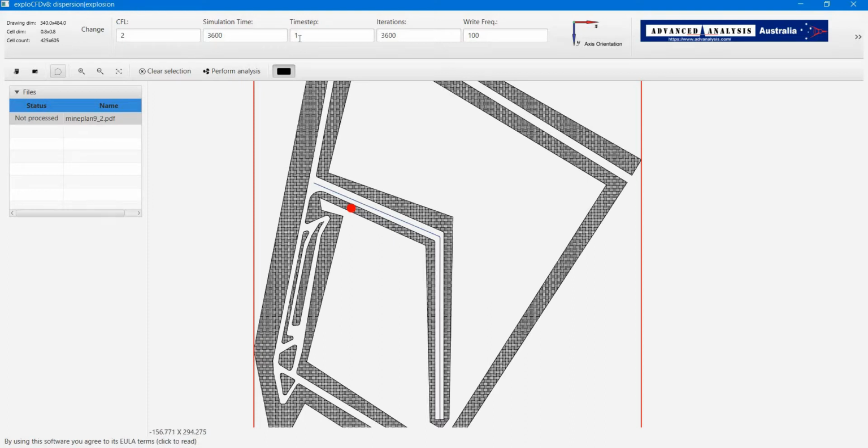So I've done everything I need to set up the first portion of this, which is modeling of the methane release. Again, the methane release is due to a failure of the ventilation in this shaft, so in other words, it's a methane accumulation more than a release. Then we're going to take a look at the results and see if we have a flammable gas cloud. If we do, we're going to ignite it. And if the pressures are high enough, we may have to model a dust cloud as well. So I'm going to perform analysis, and we'll see you when we get back.